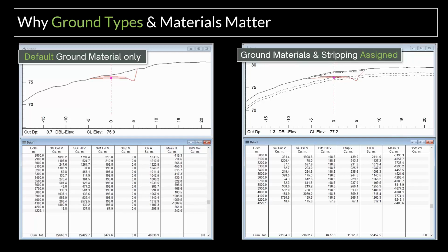And at a glance, it looks like we're only cutting 1,000 more cubic meters in that subgrade cut. But keep in mind too that we're stripping out 12,000 cubic meters of that beforehand. So our total cut has gone up a lot. Now our fill goes from being 22,000 cubic meters to almost 30,000 cubic meters. So it can be a big deal. We've got a deficit now.